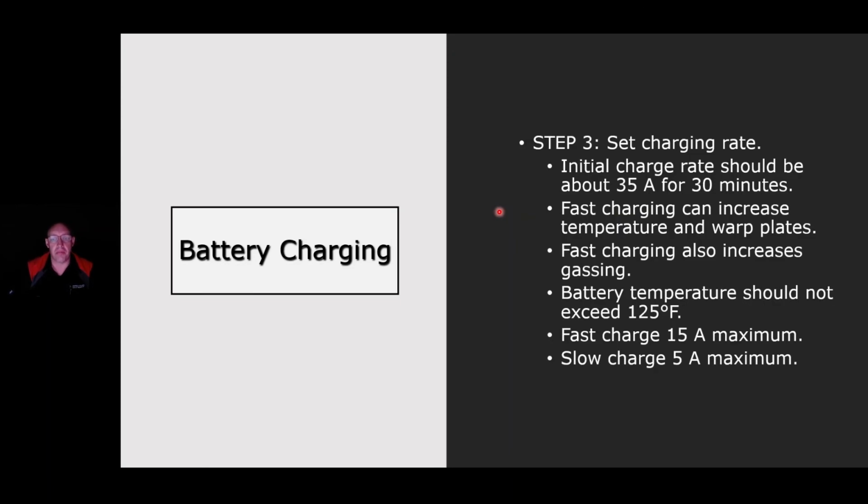But I'll put out a battery that the case is cut out around so you can see down inside the bottom storage plates for the debris. You can see the lead plates, how thin they are. Again, electron movement creates heat, right? So we want to reduce that heat as much as possible. So the slower you can charge the battery, a 2 amp or a 6 amp charge rate is better for the battery, much better for the battery than a 30 or 40 or 80 amp or 200 amp charge.